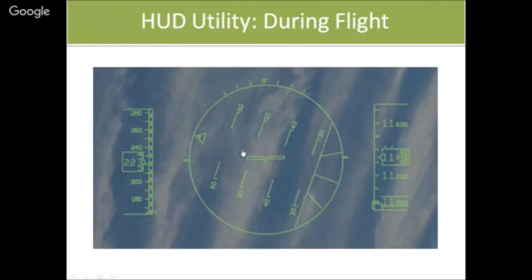Now this is basically the automatic declutter mode, wherein this page pops up when the pilot is in a gimbal lock type of situation. Gimbal lock, if you read, is basically in a gyro when two axes become parallel. If they become parallel, you move into the third axis and one degree of freedom is lost. You're not moving in XYZ because YZ has become parallel, then you have only the XY axis. In those scenarios, HUD gives you a visual solution for coming out of that gimbal lock type of situation.